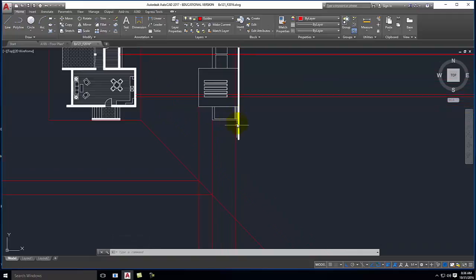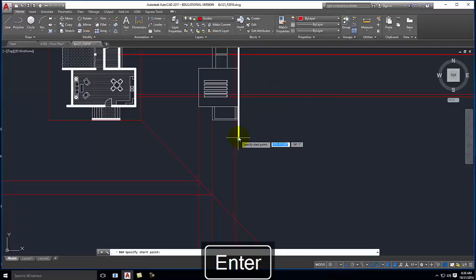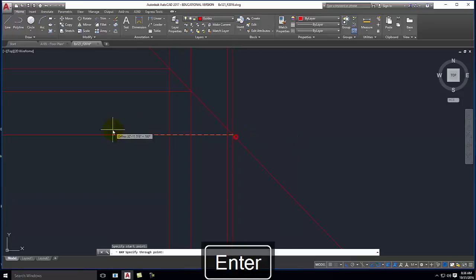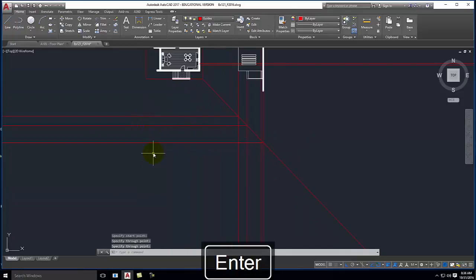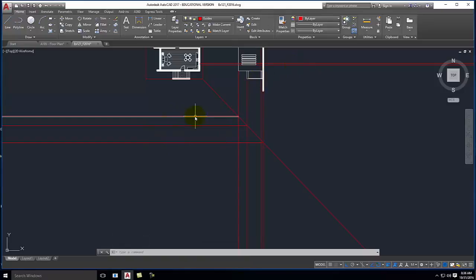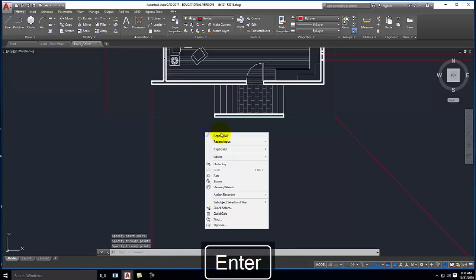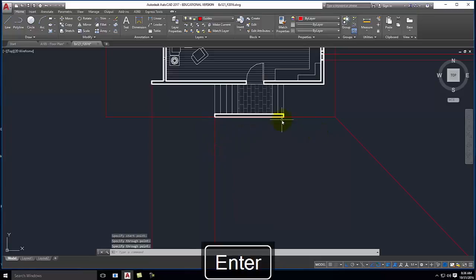I also want the base height, or where I set my ground. So I will once again type ray, and we'll go down, and we'll repeat the ray going that direction. So now I have the base, the height of the stairs, and the height here of the top of the building here. So let me go ahead and pull some lines down. So I'll use the major corners. We'll start there. We'll start right here. We'll start right here. And we'll start right there.